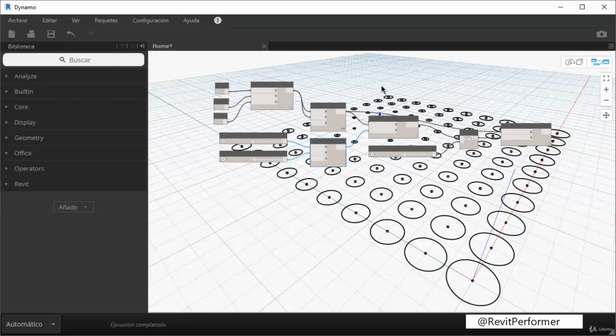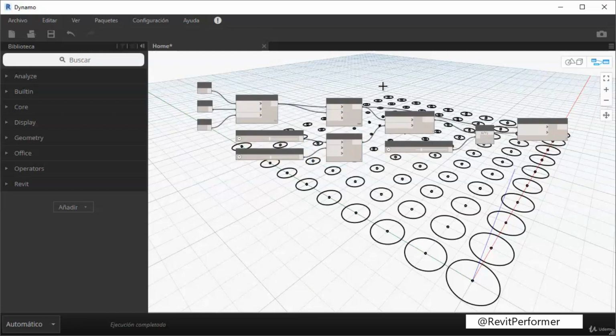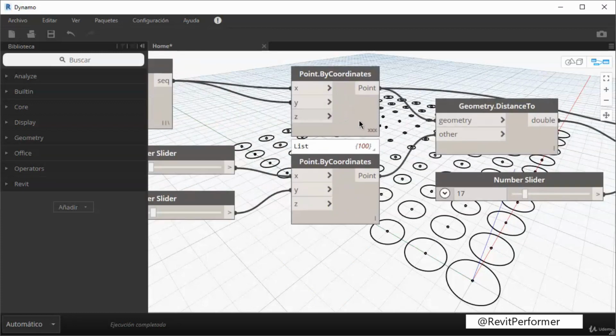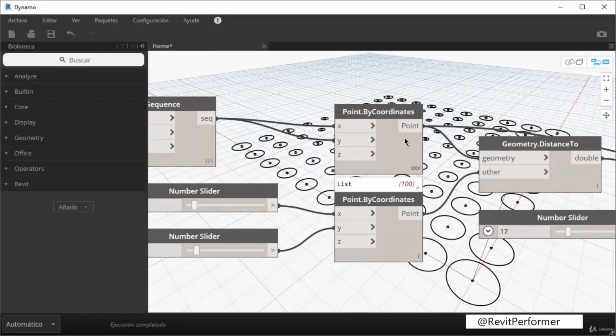If we want to keep the code tidy, we can press Ctrl L again, having selected everything. This way, we have seen how simply a node, although it says to create a point, it can create several if there are multiple entries. Perhaps one important thing to remember is that we can use the lace to change the way the data we are entering will be handled internally.